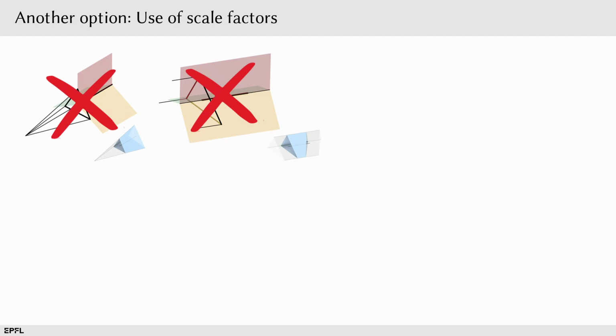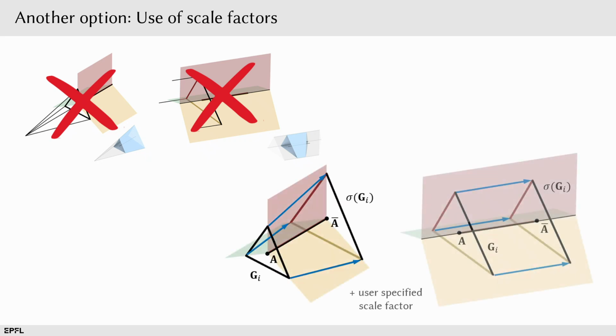So what we can now do, instead of evaluating these edges from cone apexes explicitly, is that we can take the last generatrix aligned polyline, scale it up with the scale factor that can be specified by the user, and then determine these edge directions from this scaling.